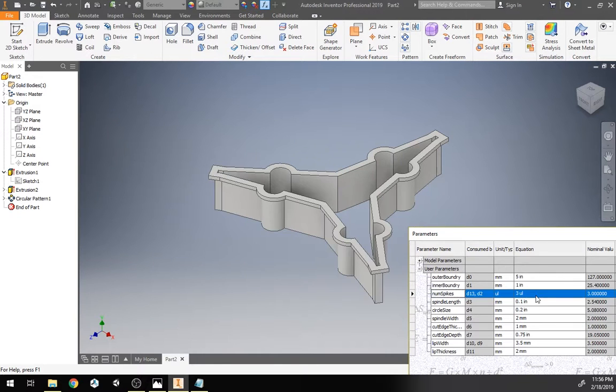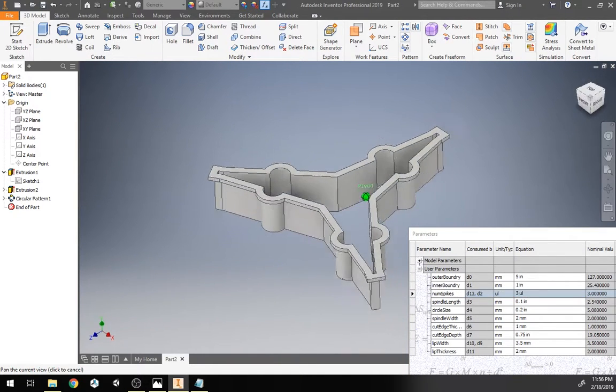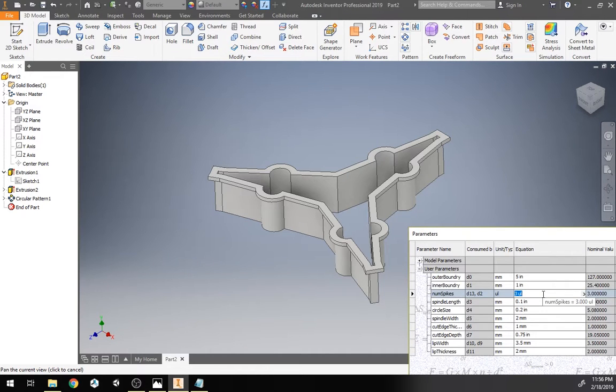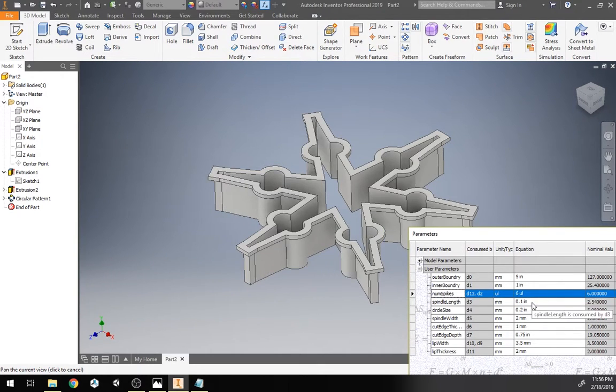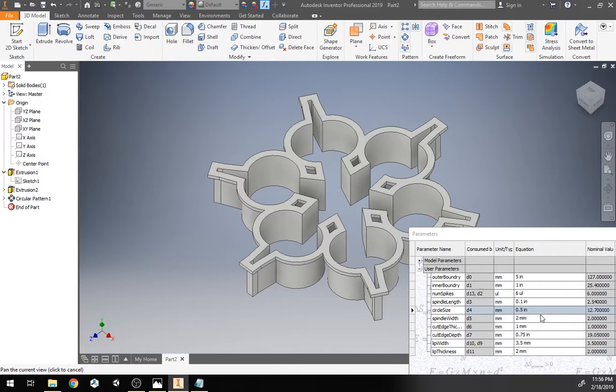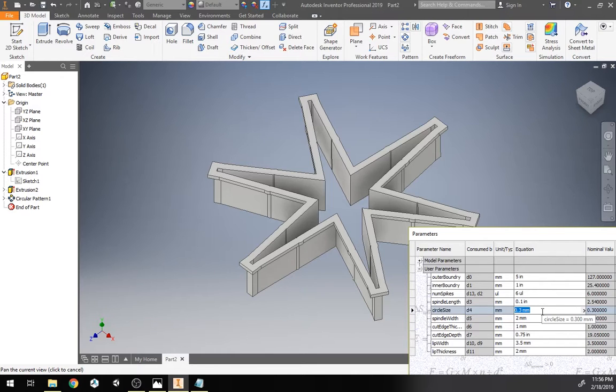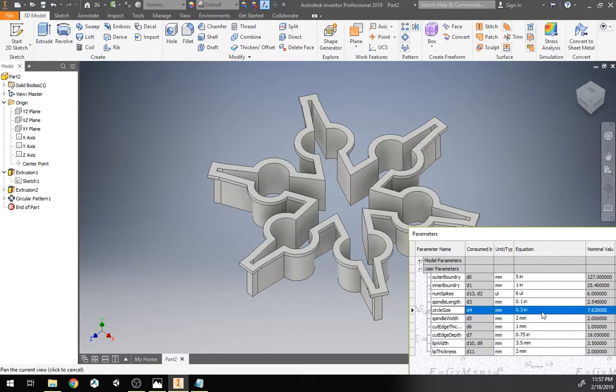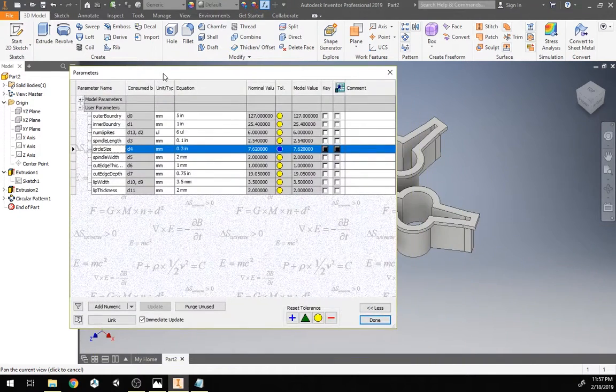And you get kind of a cross. Even 3 spikes. Now you get a ninja star. I'm going to move that up to 6 spikes again. And we'll change the circle size to 0.5 inches. And that definitely creates an interesting pattern. Maybe 0.3 inches. Oh, that's millimeters. 0.3 inches. And so the really cool thing is that you can make a very customized design by having these parameters and constraining them correctly. So you can mess with these numbers for a while.